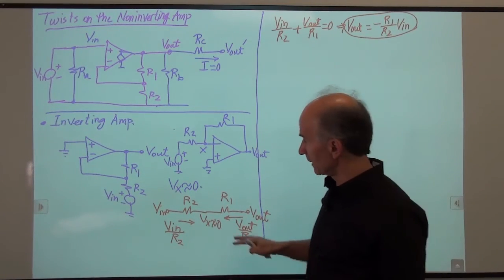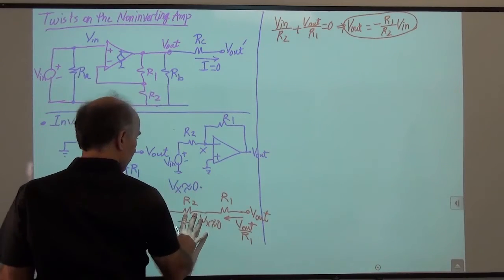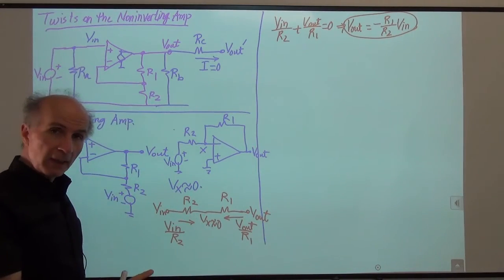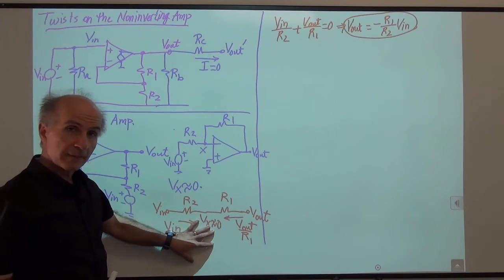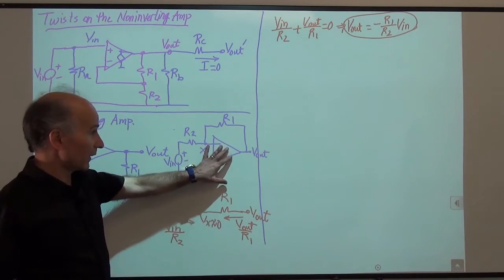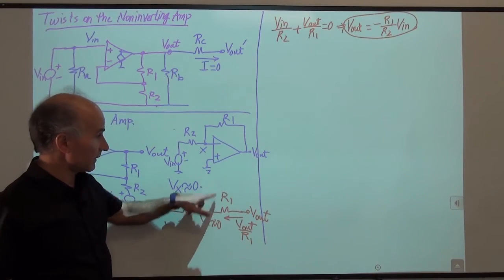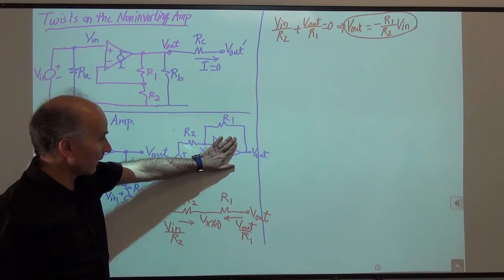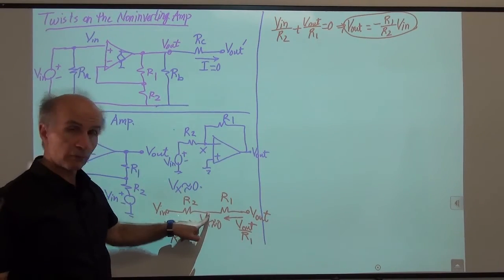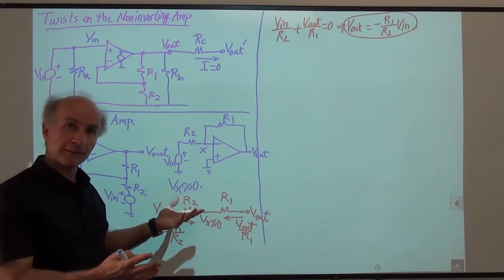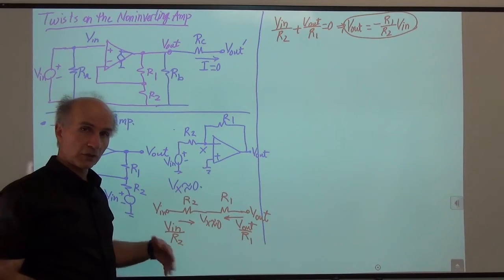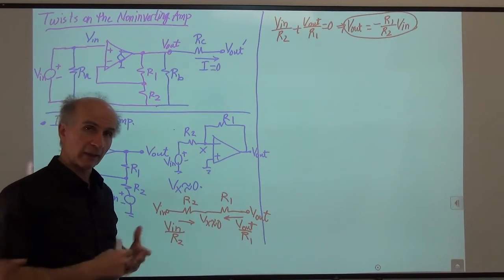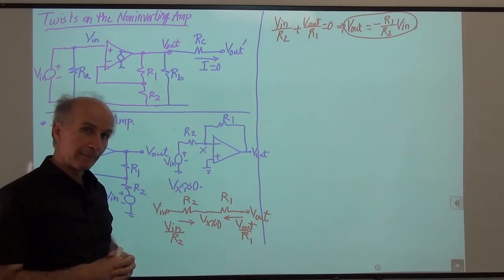All right, so you can see this methodology for analyzing op-amp circuits is very useful. I am able to simplify this circuit to this, and this is only true because we have an op-amp here. This is 0 because we have an op-amp. If you didn't have this op-amp, you could not have a 0 volt value here. It would be different, because you just have two resistors. But this simplification greatly helps us write the equations quickly and see what happens.